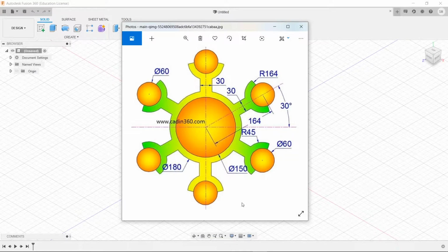Now, this was something that eluded me at first when I started learning this program, but I've since found it's super helpful to use. So, what we need to do is draw this whole object, and I personally don't want to draw each of these 1, 2, 3, 4, 5, 6 limbs individually. Limbs. And, sorry, I said that weird. But it would take forever to do that, right? So what we're going to do is use the circular pattern tool. So let's get to it.